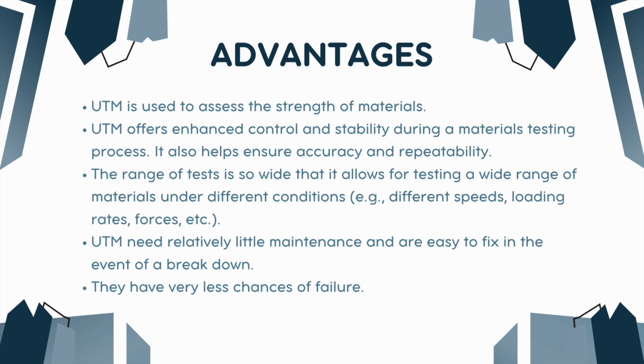So the advantages: it assesses the strength of materials, and UTM offers enhanced control and stability during the materials testing process. It also helps ensure accuracy and repeatability. The range of tests is so wide that it allows testing a wide range of materials under different conditions, different speeds, loading rates, and forces.